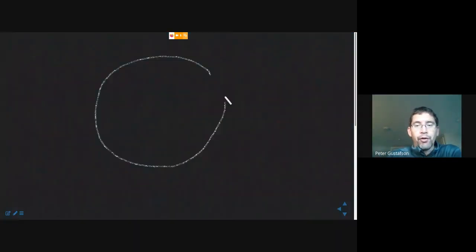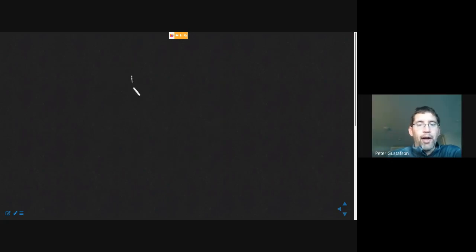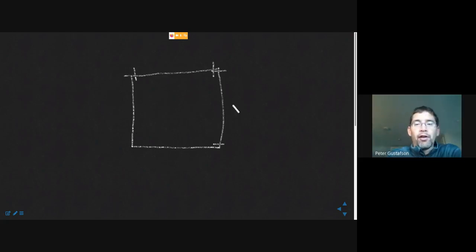So, again, as you go around the circle, or it doesn't have to be a circle, the differential length ds has a different direction at different points in the circle. Here it's up and to the right, here it's basically to the left, here it's down and to the left. Since q is a magnitude, the vector qds is going to be different in direction at every point. Now, I shouldn't say at every point, because I have to be careful about that statement. If I draw a square, then everywhere from here to here, the direction will be the same, and everywhere from here to here, the direction will be the same. But it's all relative to the center of twist, and this radius to the center of twist defines how much of that shear flow contribution actually contributes torque.